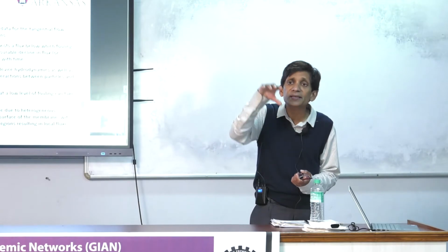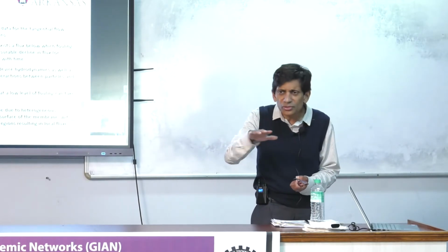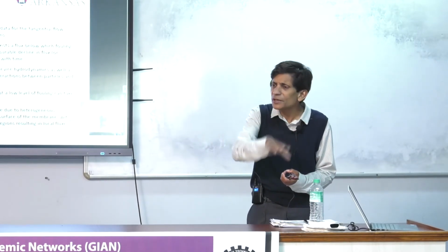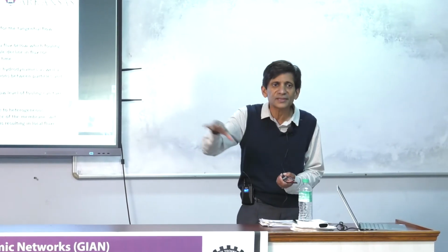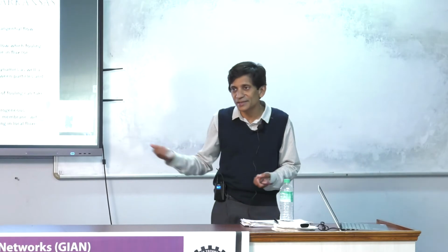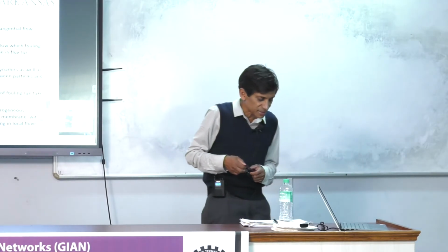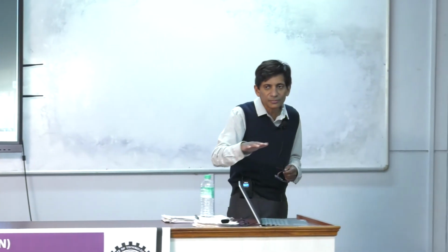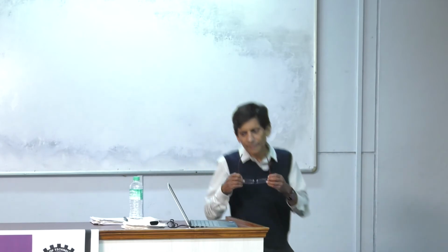So some places you might have higher fluxes on a local basis than other places, right? Where you have higher fluxes, you might get more fouling than other locations. And so this leads to basically fouling and this low level of fouling we're talking about. So you don't have a perfectly uniform membrane, you don't have perfectly uniform particles, and you don't have particles that are non-interacting, okay?